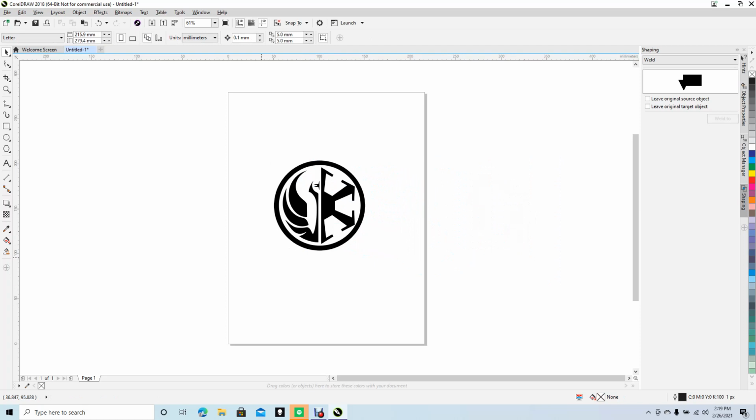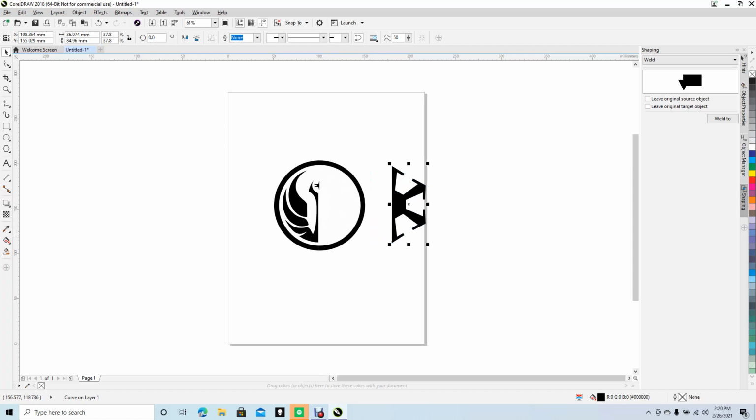Now, sometimes Corel Draw, when it traces, puts a line on top of a line. You want to be careful of that, because if you import this over to FreeCAD and then to Design Sparks Mechanical, it's not going to fill because there will be two lines there instead of one. To remedy that, you want to do Control U, which is ungroup. You want to click on the various elements and move them out of the way.